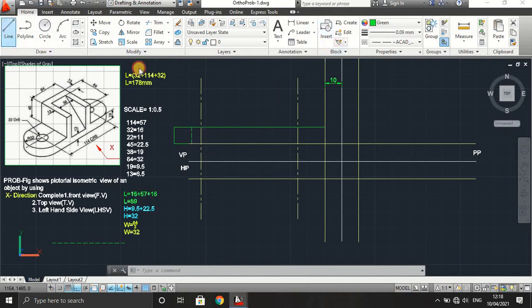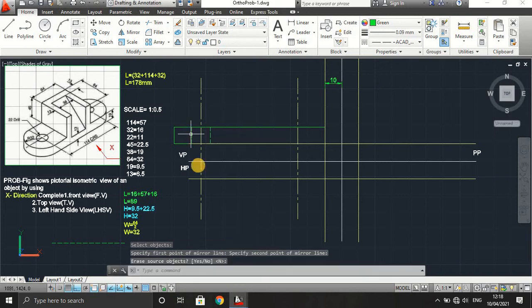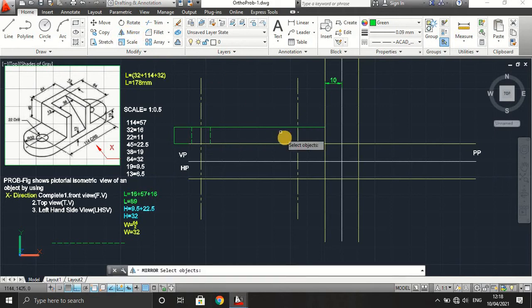In a similar way, the total hole diameter, show two dotted lines for the hole that is invisible in front view. The same we can apply for the other side also. The hole from this base plate is not visible in X direction.